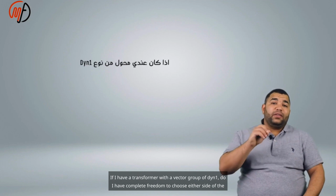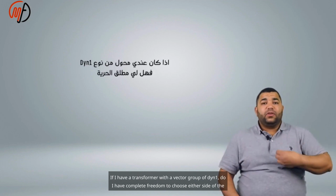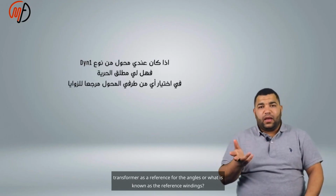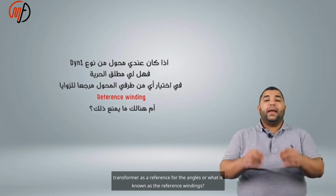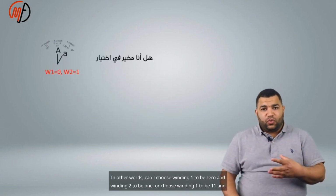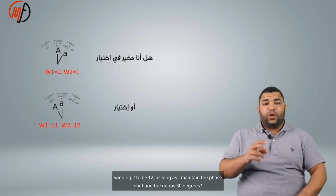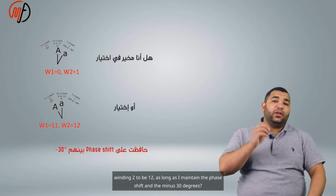If I have a transformer with a vector group of DYN1, do I have complete freedom to choose either side of the transformer as a reference for the angles, or what is known as the reference winding? In other words, can I choose winding 1 to be 0 and winding 2 to be 1, or choose winding 1 to be 11 and winding 2 to be 12, as long as I maintain the phase shift of minus 30 degrees?